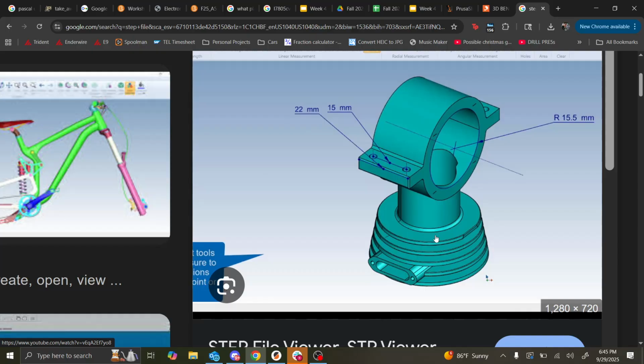A long time ago, slicers could only read STL files, and one time I printed this really large cylindrical object, and you could see the little triangles inside the model. But if I was using a STEP file, then it would still be completely round. So keep that in mind.